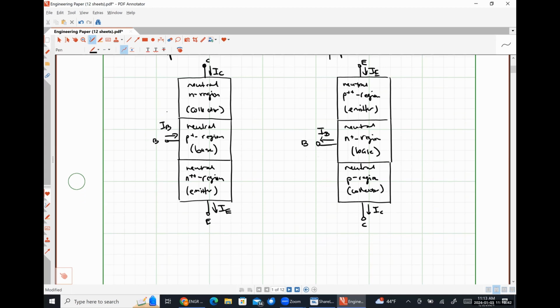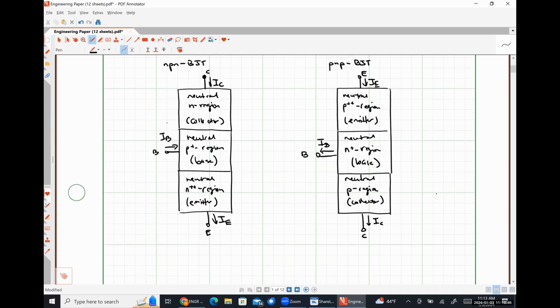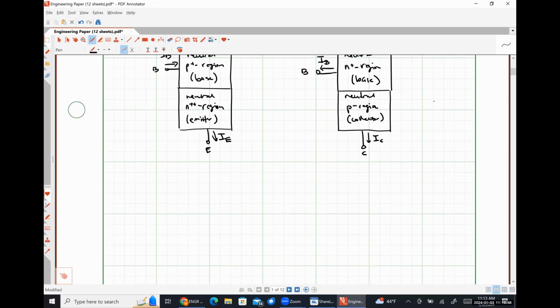And then because it would be a pain to do circuit analysis using this particular model, I'm going to give you the schematic diagrams as well. So for an NPN BJT, we're going to have our collector on top, our emitter on bottom, and then our base here in the middle. And this is an arrow indicating that our emitter current is flowing out of the device.